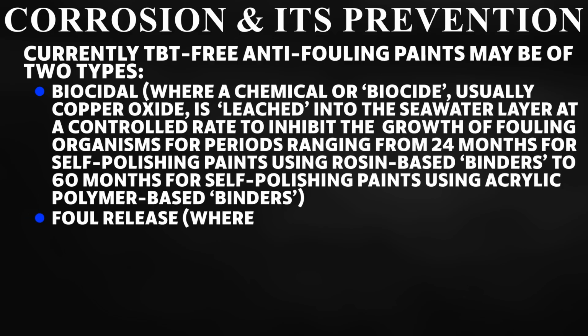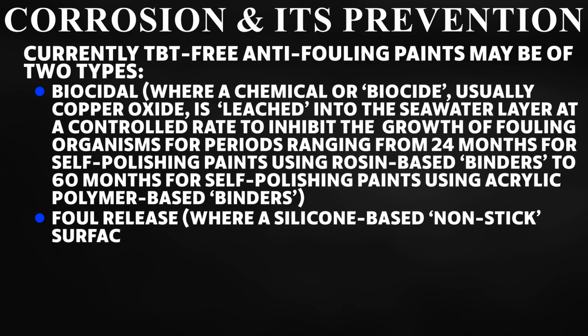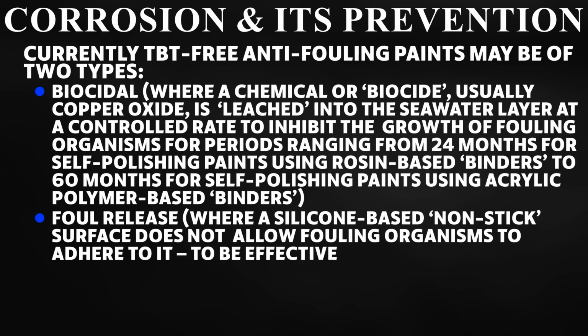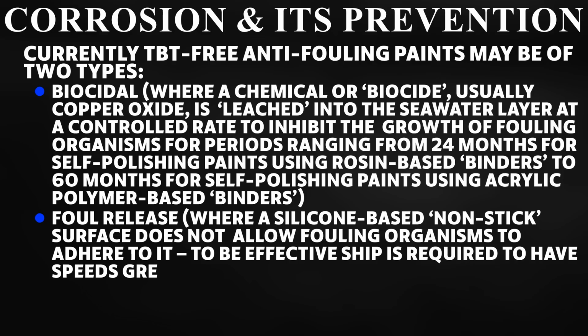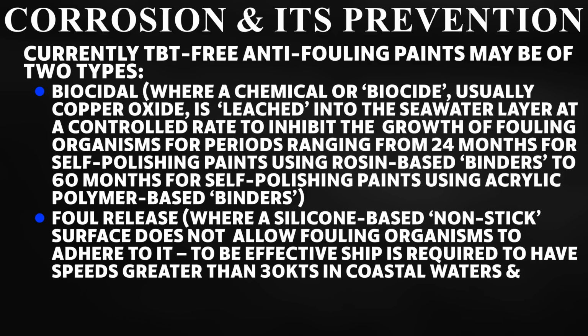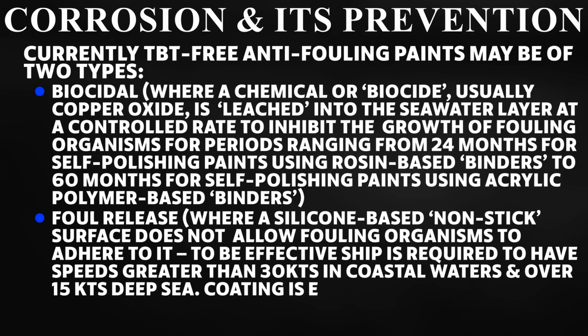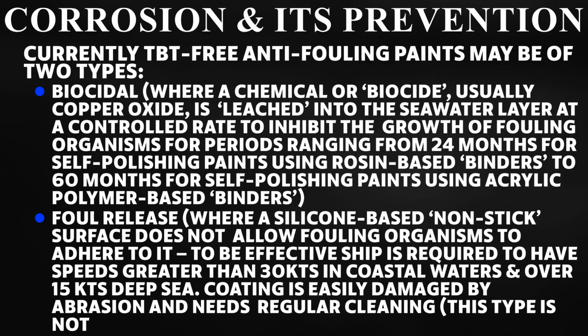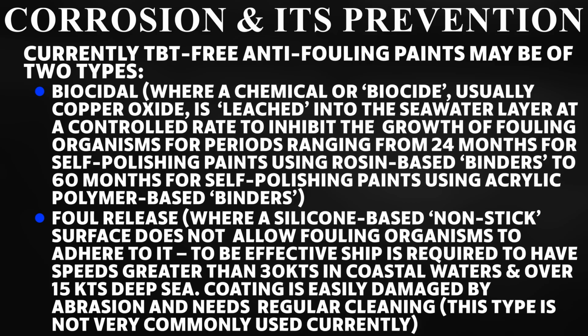Foul release, where a silicone-based non-stick surface does not allow fouling organisms to adhere to it. To be effective, the ship is required to have speeds greater than 30 knots in coastal waters and over 15 knots in deep sea. The coating is easily damaged by abrasion and needs regular cleaning. This type is not very commonly used currently.